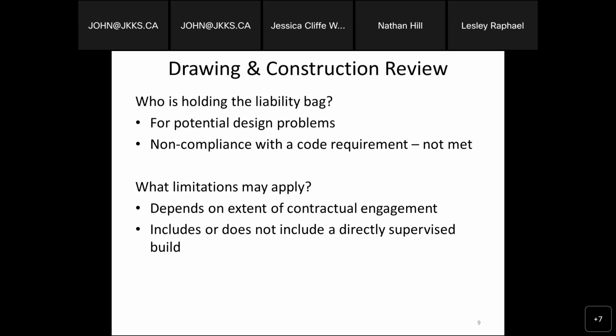So this comes down to risk assessment. It also comes down to the agreement, as I indicated, between the architect and engineer and the actual owner. If you're going to have oversight on the work, you have to be sure to have sufficient supervision to oversee the project to make sure it's done properly and according to drawings and the specifications. So the extent of the supervision must be defined by the scope of work, but not less than a reasonable standard for professional care.